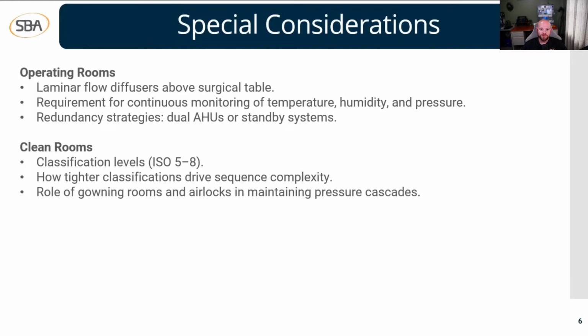Remember, this is an operating room. A big thing in these spaces is keeping out any kind of infections or contaminations. Remember, they may have someone in there on a table that they're operating on and can't have any kind of particulates or anything getting into that room. So positive pressure is huge, and temperature and humidity control are really big things with operating rooms.